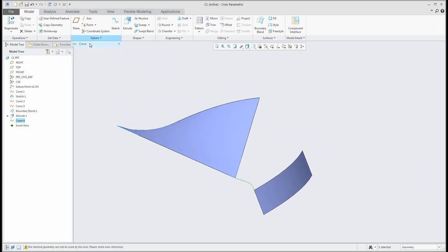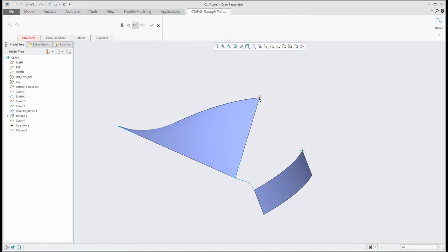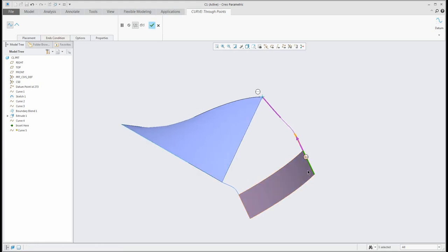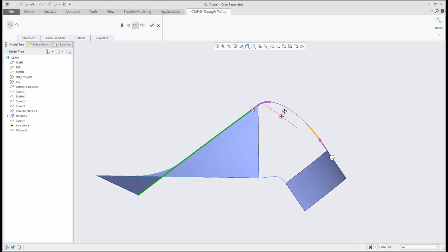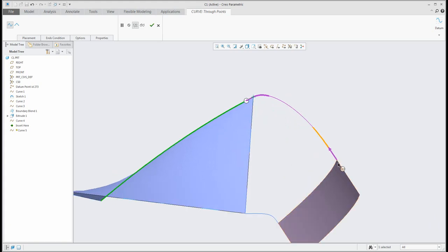If I would like to continue with another curve, I will select and specify the curve between two points, and again really quickly curvature over here, specified on the surface edge, and over here I will specify tangent on that edge but the opposite way. So right now you can see here that the system will create for me the curves which are connected directly to the surface and that edge, and the opposite way it's the same.